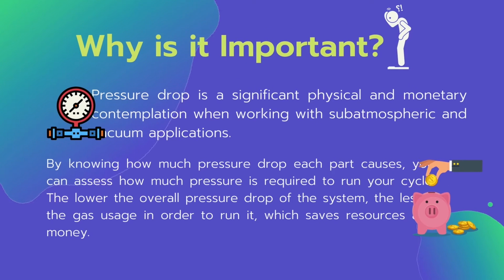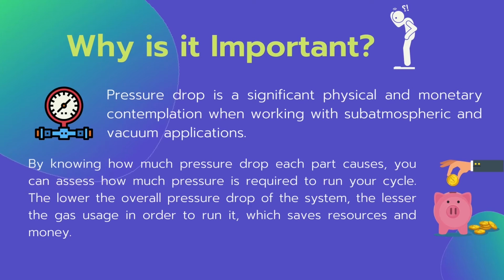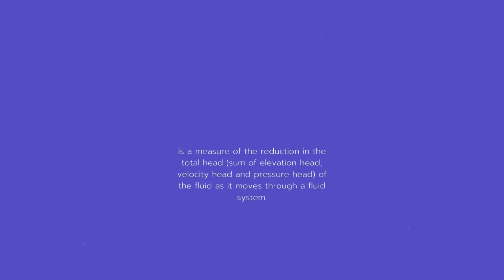Pressure drop is a significant physical and monetary consideration when working with sub-atmospheric and vacuum applications. By knowing how much pressure drop each part causes, you can assess how much pressure is required to run your cycle. The lower the overall pressure drop of the system, the less gas usage in order to run it, which saves resources and money.